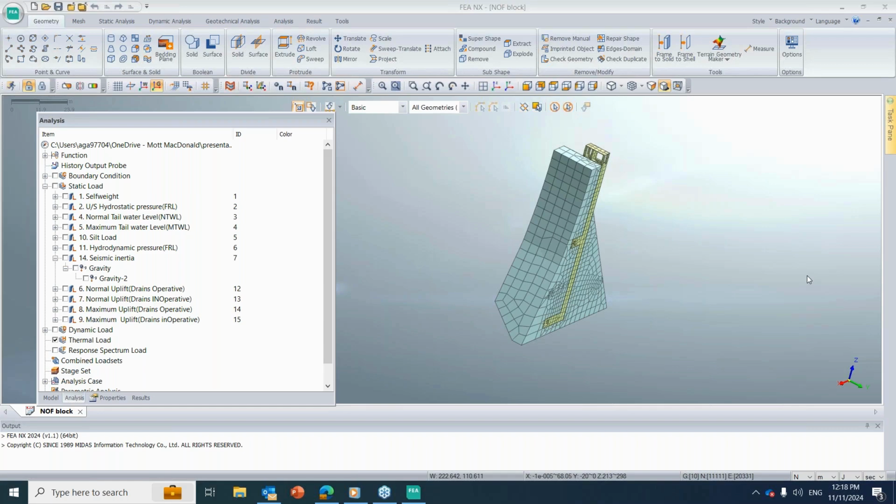Whatever constraints we have applied on the model will define the boundary constraints for the direct time history method. So it is not dependent on mode shapes or whatever. I'll show you in the next session. We'll go through that code and I'll show you that. So eigenvalue analysis is not required for the direct time history method. Thank you, sir.